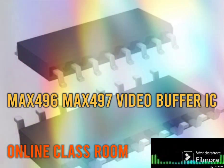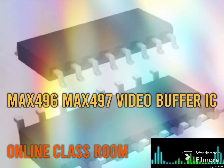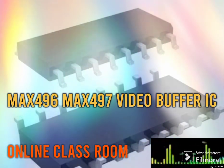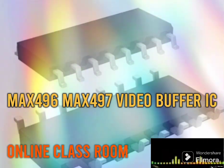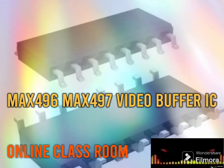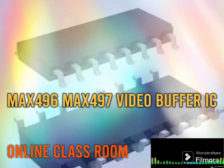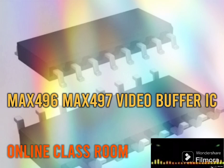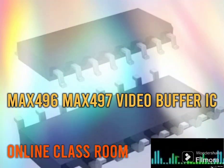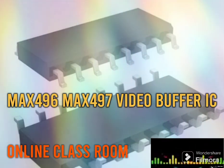excellent output current capability and fixed gain of plus 2. It is specifically designed to drive 50 ohm or 75 ohm coaxial cable to plus or minus 2.8 volt. In a typical application, the max497 is used to drive a back terminated 75 ohm video cable. The back termination resistor at the max497's output matches the impedance of the cable's driven end to eliminate signal reflections.